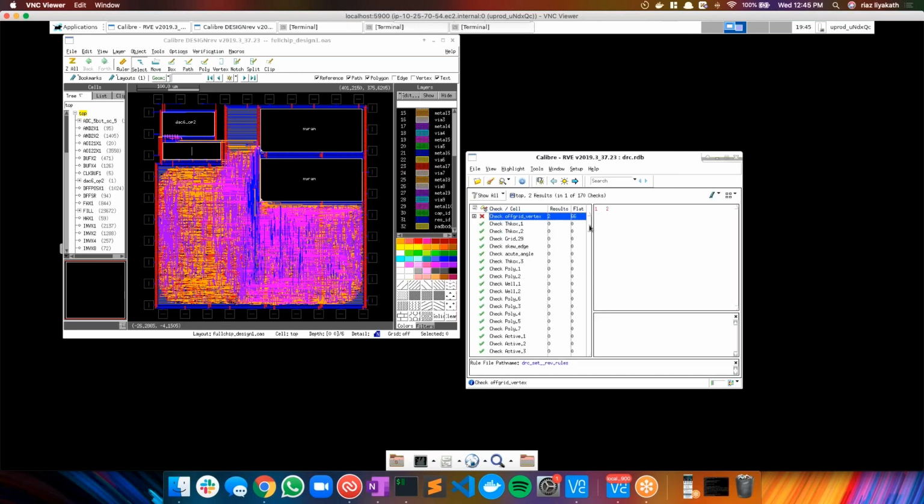So this shows the results for design A. To recap, we had 3 designs. I was pretty confident that the first design would pass because it was a very conservative design, so I'm not surprised with the results. You can see that almost all of my layout passes DRC. The first 2 are just off-grid vertexes, which we can ignore.